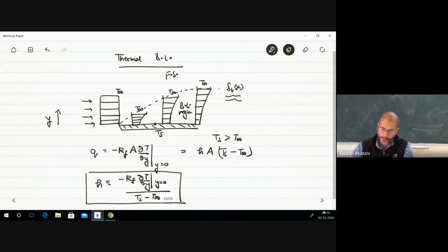And again, how do we define this temperature boundary layer? So delta T is defined in such a way so that 99% of the effects because of the surface have penetrated into the fluid. So the maximum difference between temperature that we have here is T infinity minus Ts, and we're talking about 99% of those effects being penetrated. So we call that T minus Ts over T infinity minus Ts is equal to 0.99.